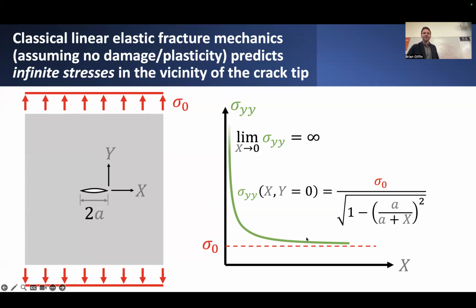So, assuming that the material behavior exhibits this kind of asymptotic trend towards an infinite stress in the vicinity of the crack tip, that's part of the reason why it's not such a great idea to work with purely stress-based measures of failure, especially for fracture, as you get into these kinds of domains.